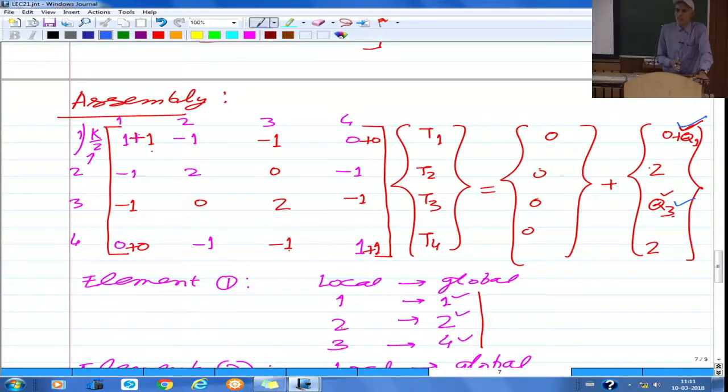But we must understand that when we are writing the element level governing equations, those terms are actually there. But finally, in the assembled system, if you leave it as it is, then you would find, as in many books, that reaction fluxes, or in the case of mechanics problems reaction forces and moments, are not taken into account.